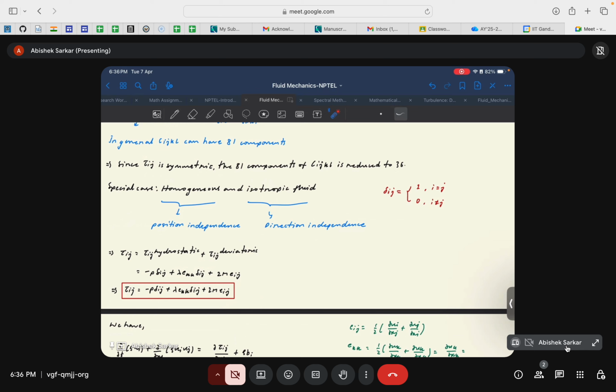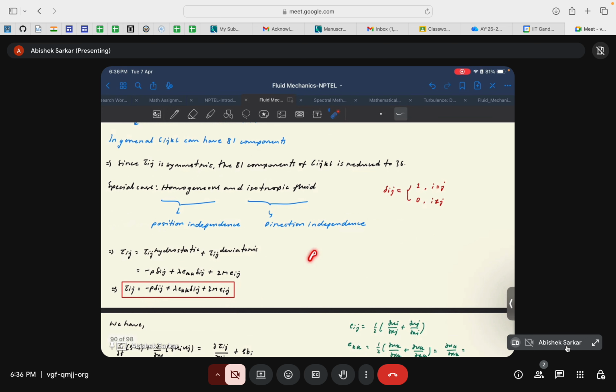But my understanding is that in a very simplified case, it generates a second order tensor from a scalar field, of course keeping the mathematical interpretation of these tensors intact. So P was just a scalar field initially, but this delta ij term is what makes you able to add this scalar field correctly into the second order tensors, so that the physical implications are kept intact.